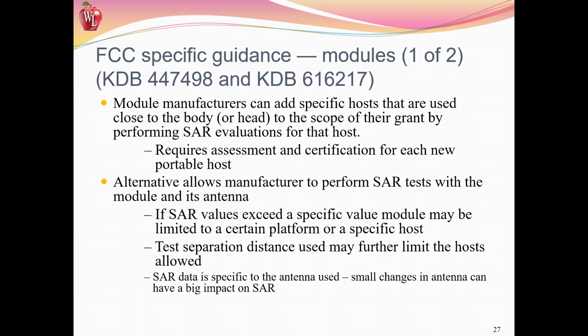Alternative hosts allows the manufacturer to perform SAR tests with the module and its antenna. If it exceeds a specified value, the module may be limited to certain platforms. Test separation distance may further limit the hosts allowed, and SAR data is subject to the antenna used.